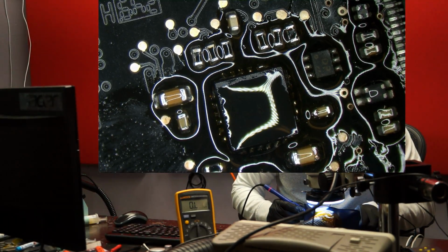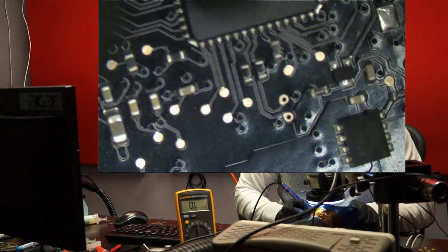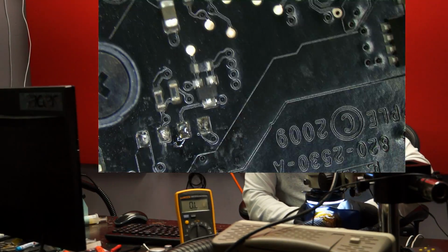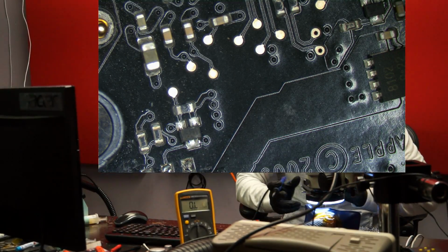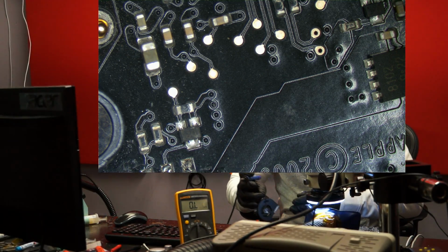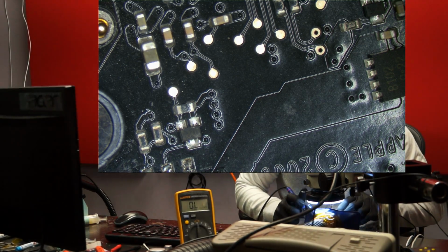Okay, and I can also see that whoever did this tried to hide the fact that they ripped the fan connector off of the board. So I'm guessing that this has been somewhere else before. You see that? Because that just came right off. And there are no pads. Lovely. So let's try and reconnect the fan connector.